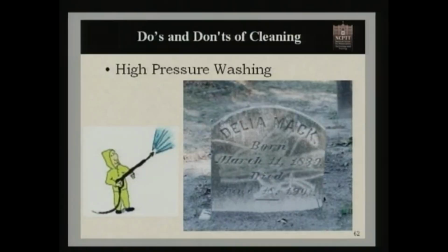Now, of course, this does a measurable amount of damage. This is very bad for historic stone. It actually rips that surface off. It grinds away that important information, that important cultural material. So we want to stay away from grinders or sanders or wire brushes of any kind when working with historic stone. Another thing that we want to stay away from is the pressure washing.